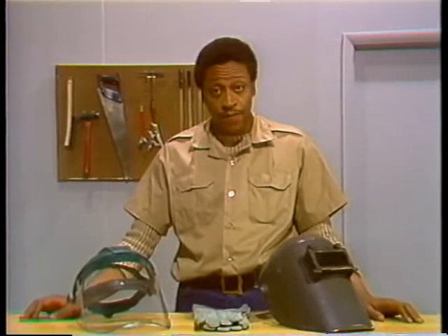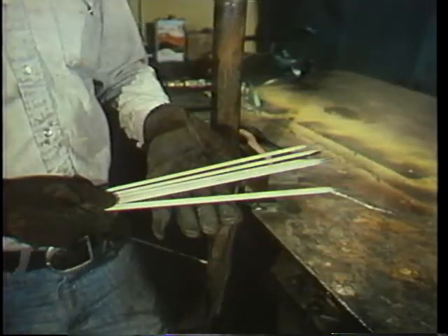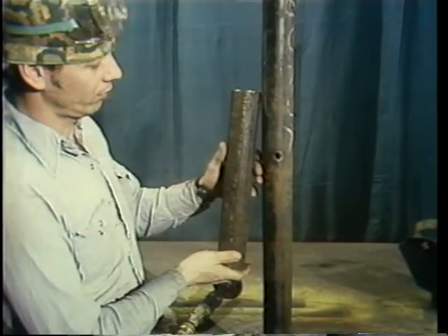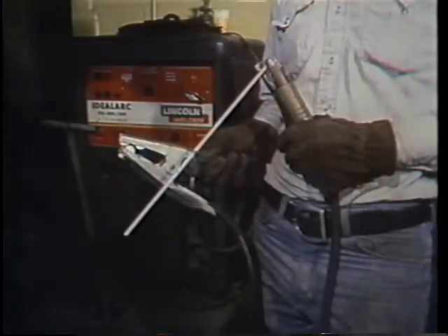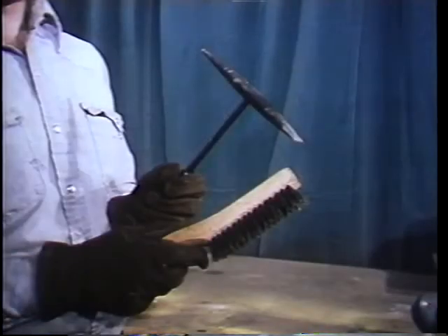Then, get your materials and equipment together. You'll need some welding rods and a length of tube from which to cut a replacement piece. The replacement tube must be of the same size and material as the original tube. Check your boiler manufacturer manual to find out the makeup and dimensions of the original tube. For equipment, you'll need a welding machine with a rod holder and grounding cable and the usual welding tools, a slag hammer, and a wire brush.